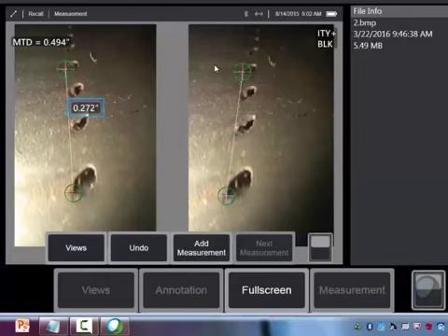There's always some level of small error in this selected match position. And because the horizontal spacing is used to calculate the 3D coordinate, that match error creates some level of computed 3D error. Now, this matching error varies from image to image and pixel to pixel. And that variation will cause variations in your measured result.